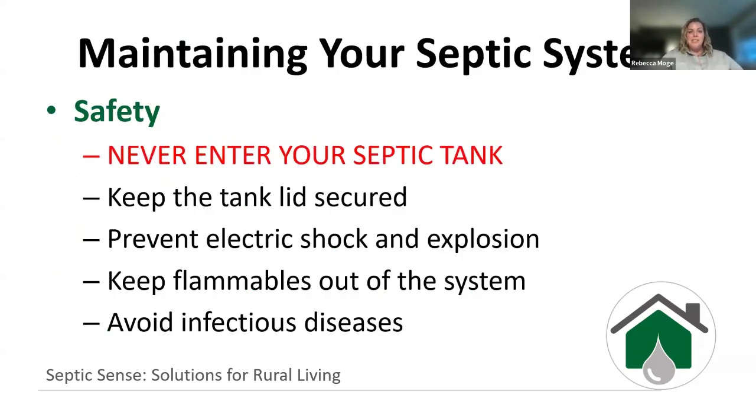So, safety when dealing with our septic tank. Maybe we're trying to maintain it or things aren't working properly. What do we do? We will never, ever go into your septic tank. In order to enter a septic tank, there's specialized certification, equipment, masks, all those kinds of things that are required. So never, ever enter a septic tank.